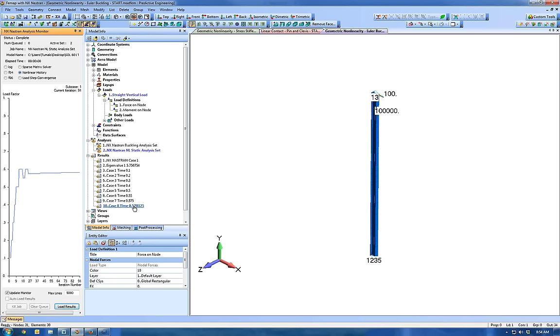Now, something that I want to talk about, it'll be a bit of a self-study, is exactly how much instability do we instigate in the model. You know, what if my bending moment was 10 pounds, or what if it was 1,000 pounds? And what I've found in this model is if you start low and work your way up, you can actually converge on a value that will mimic your hand calcs or your linear buckling analysis.